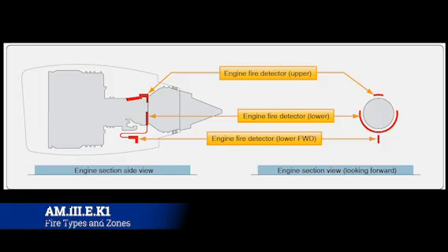And then you have the combustor, turbine, and tailpipe section. So that obviously gets super duper hot, so it being a fire zone in and of its own accord makes sense. Now, in addition to the engine and the nacelle zones, other areas on multi-engine aircraft, like your big heavy commercial aircraft, are provided with fire protection and detection systems. These are like baggage compartments, lavatories, APU, combustion heater installations, and other hazardous areas. Depending on the configuration and purpose of the aircraft, you can potentially have additional fire zones as well.